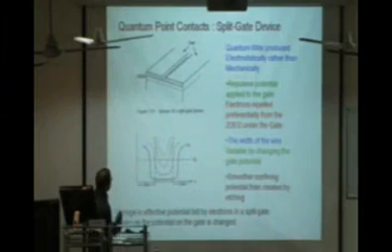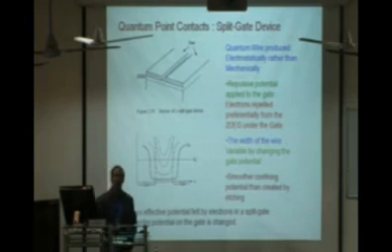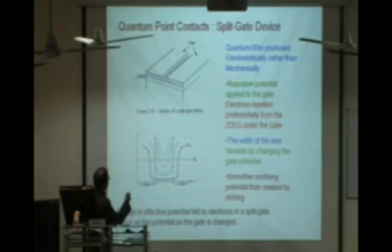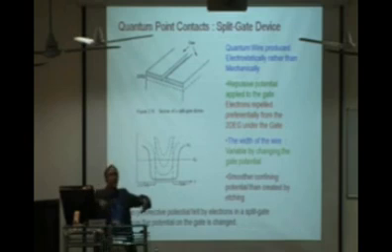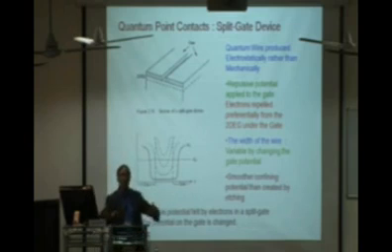In fact, this is some kind of structure called a MOSFET structure. We put two gates, one gate here and the second gate here, and below this you have some kind of quantum well, which we call a two-dimensional electron gas system. When you start biasing the gate in a semiconductor, depletion takes place just below the gate.